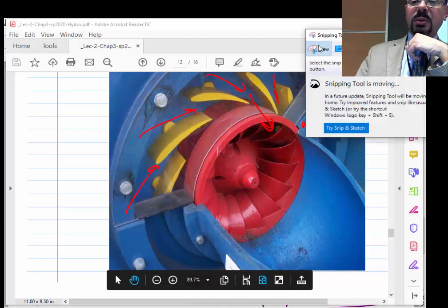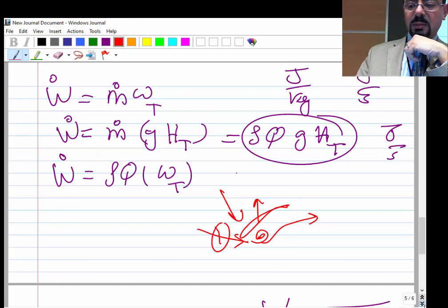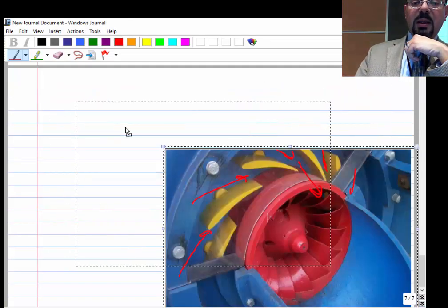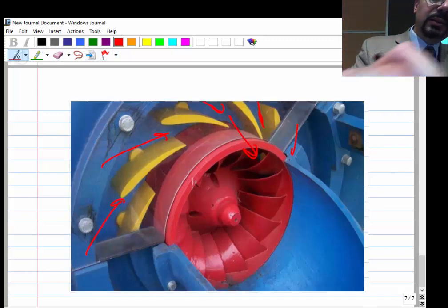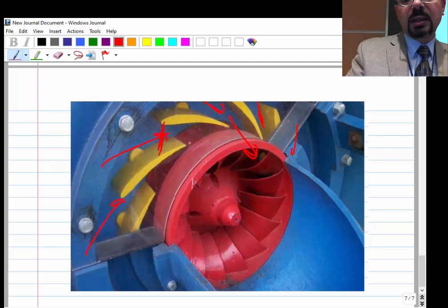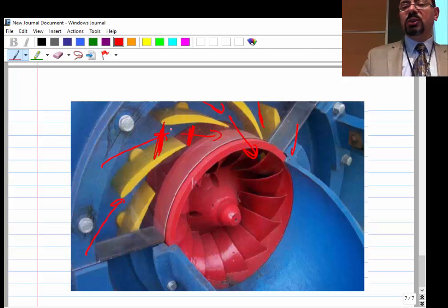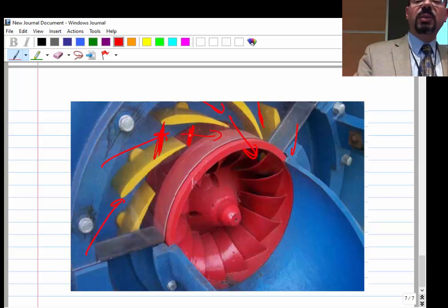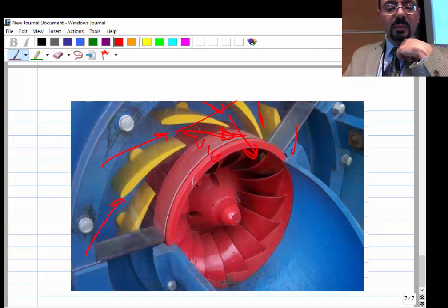And the nozzle part is because if we plot the inlet area, it would be this, and the exit area would be like this. So you can see how this is much bigger than this. So the flow really goes into a nozzle, right? This geometry basically drops the pressure and increases the velocity. Not only increases the velocity, but makes it such that it's V1 theta basically. So the tangential component becomes really big.